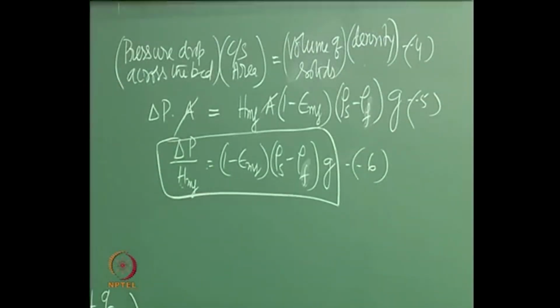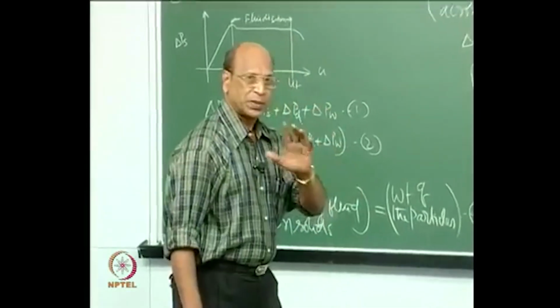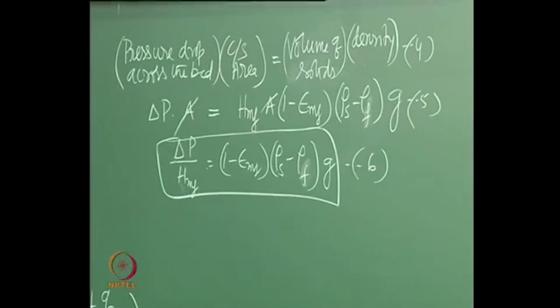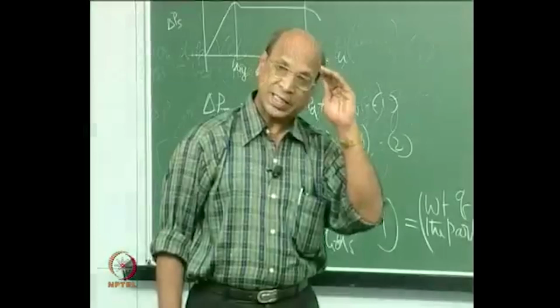So, this will give you an idea. I told you sometime back, I think it was Anurag who was asking me, the pressure drop in a fluidized bed may be higher than the packed bed. See, the maximum pressure drop you get is only this here, due to solids. But the distributor will always have an increasing pressure drop as you go.